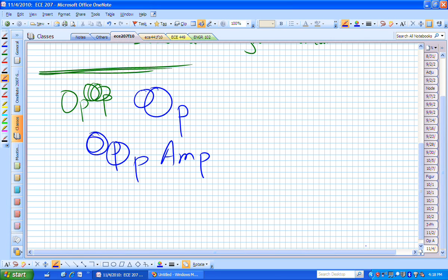And you may want to give yourself a little bit more room than what I did up above your triangle. I now have a resistor there, another resistor here to ground, a resistor there, and all of that is in my feedback path. And here is now my output voltage V0, my load resistor R sub L, all connected to ground.